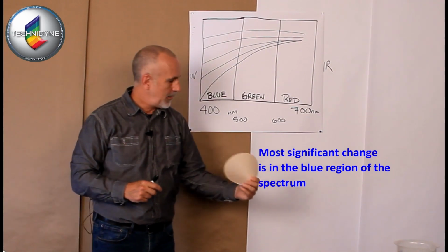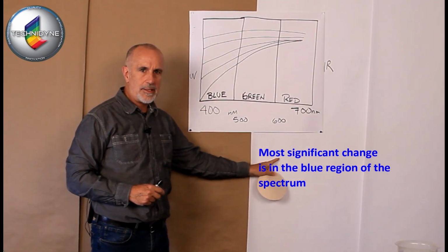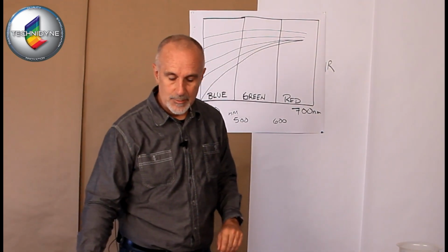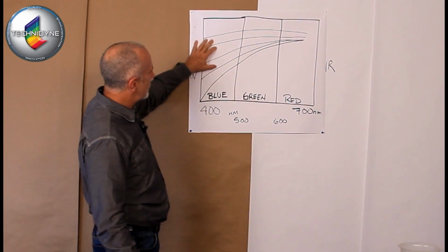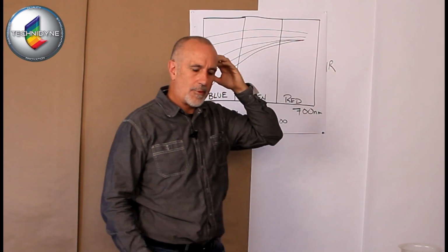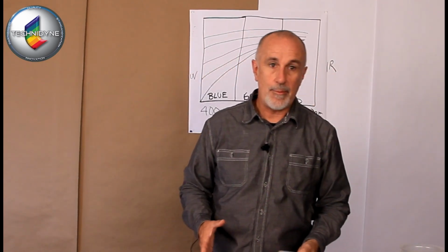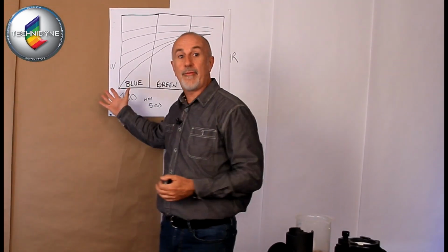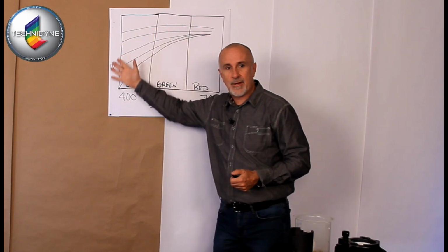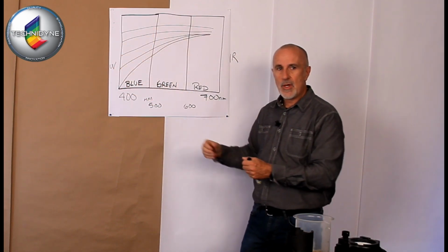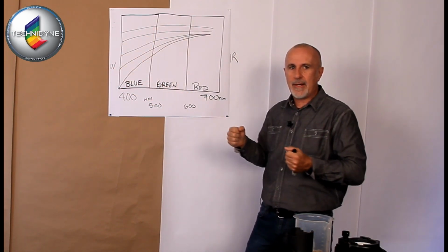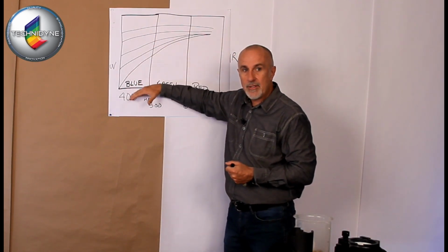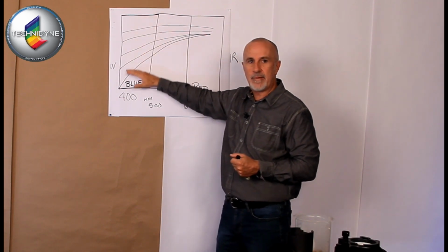Okay, so we could see this sheet going from here possibly to here, and then eventually to here, depending upon what the ultimate optical characteristic the customer wanted. So the Institute was able to gather this information off their GE recording spectrometer they had there. So then they sit down with the customer and said, okay, here's what we found. We found that this is the scenario that we have in the bleaching process. As we remove that lignin, as we remove that color from that, the sheet's getting lighter, but the greatest change is occurring here in this region of the spectrum.